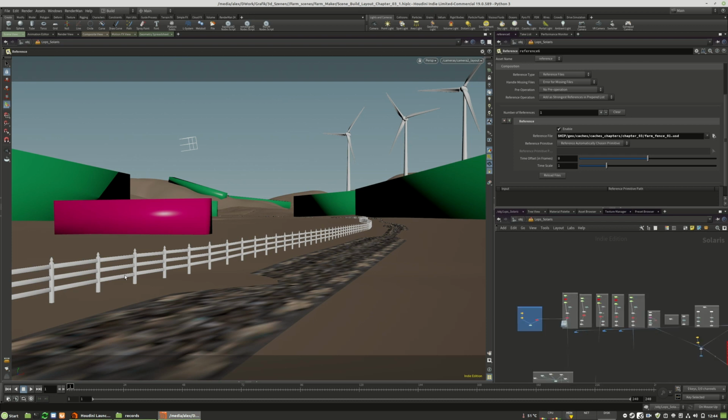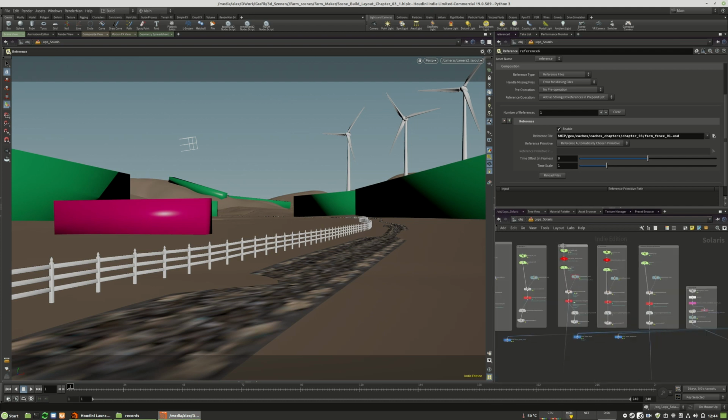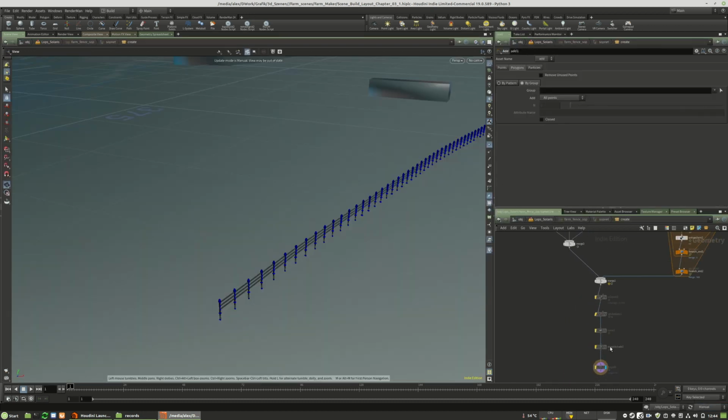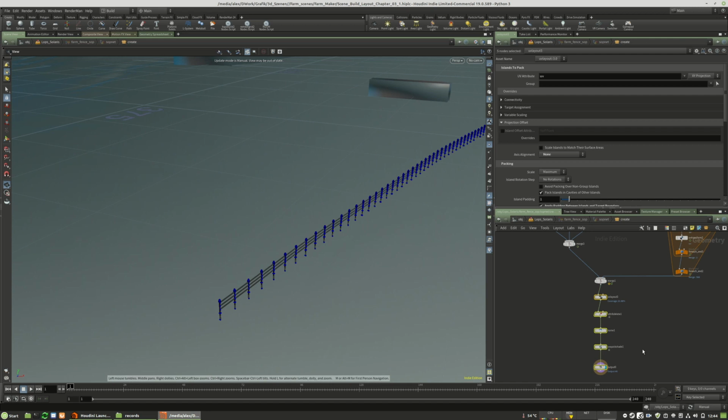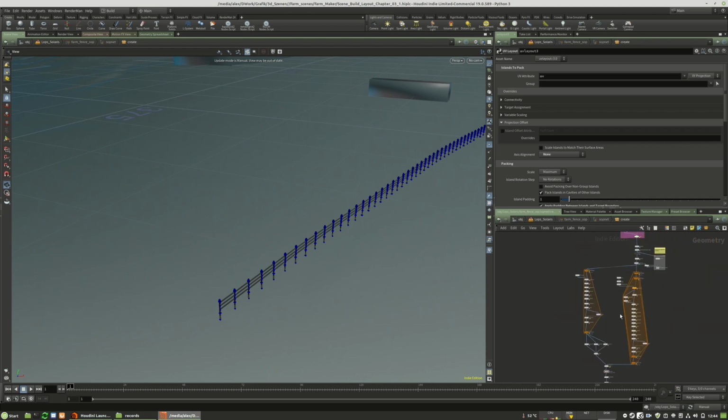Of course, we currently have deactivated the UV baking, which is the most expensive performance wise. So we switch back to manual mode, go here, reactivate all those nodes. We don't need the quick shade. And that should be it.